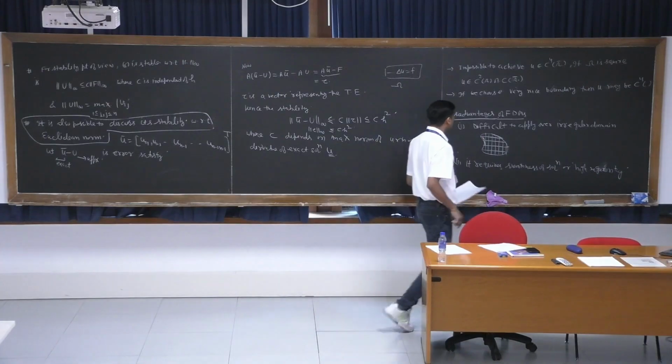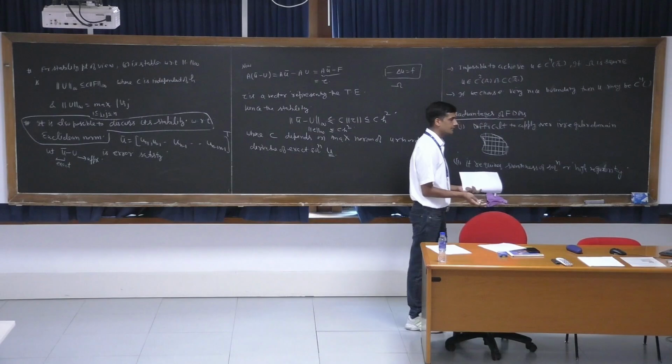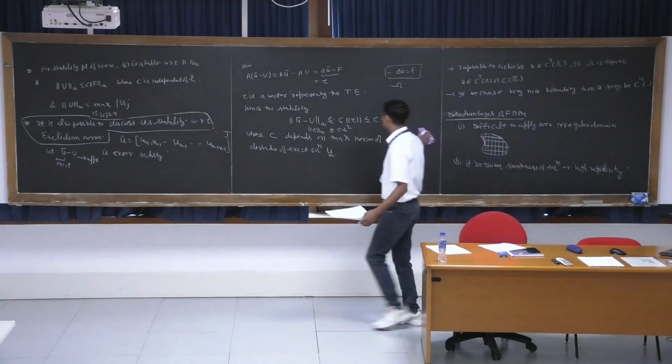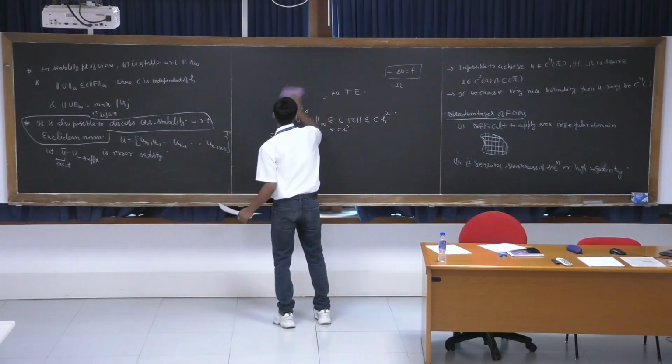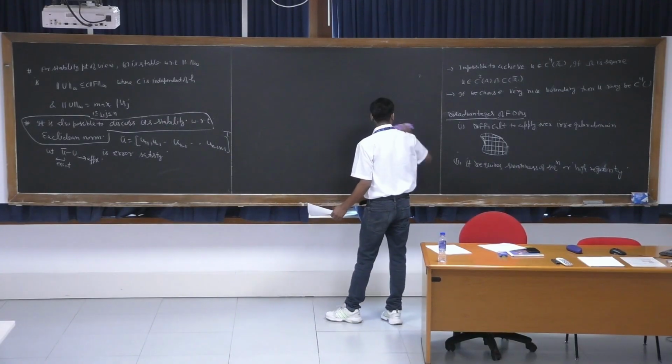Second thing, if you have to find a nice, more accurate solution, you have to refine the mesh. Refine means you have to increase the number of points.